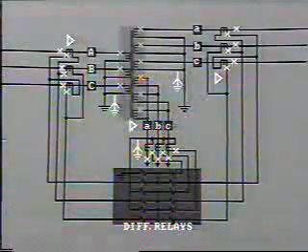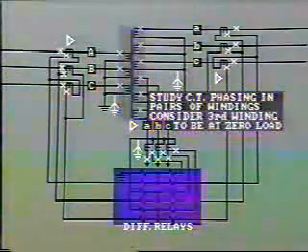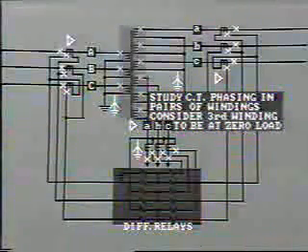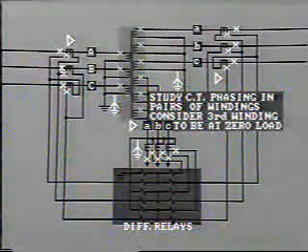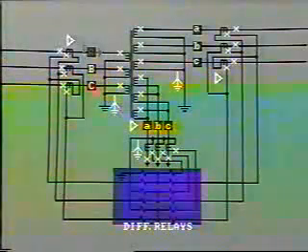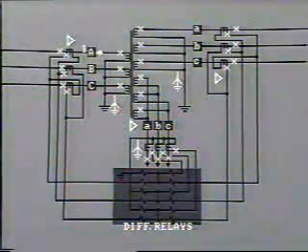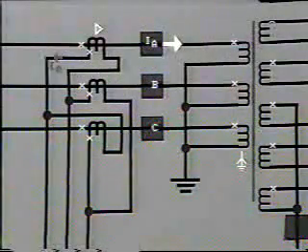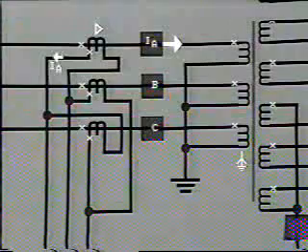When dealing with multiple winding transformers, it's always advisable to study CT phasing in pairs of windings, considering the third winding to be at zero load. Let's start with the primary and tertiary windings. Line current IA passes through the A-phase transformer primary and into the neutral. This gives us current IA this way in the CT secondary.